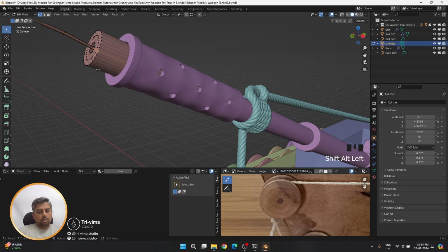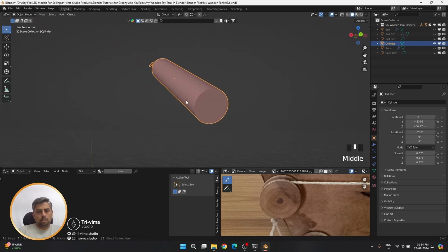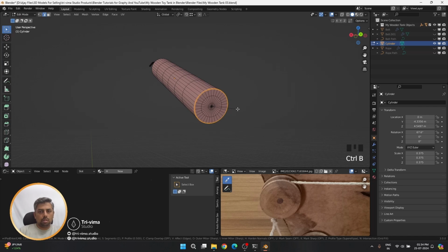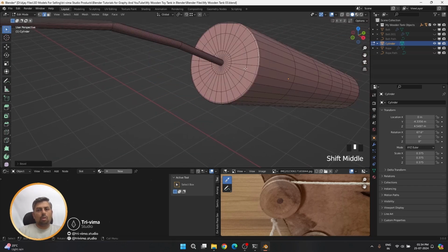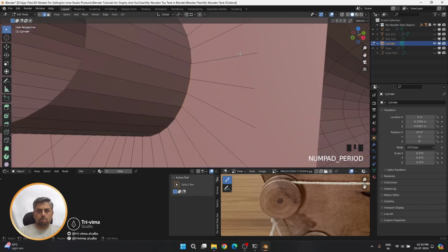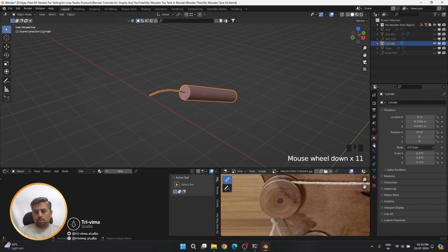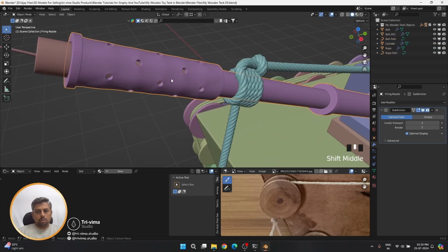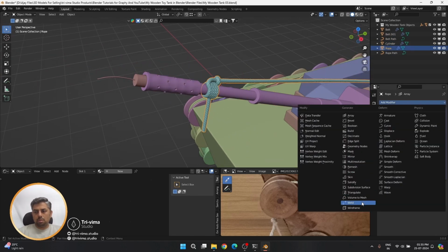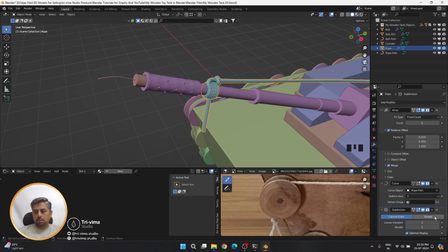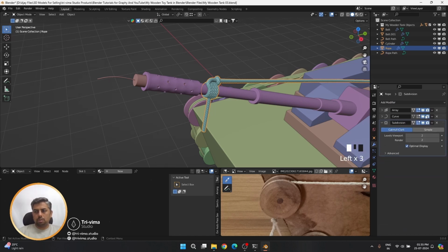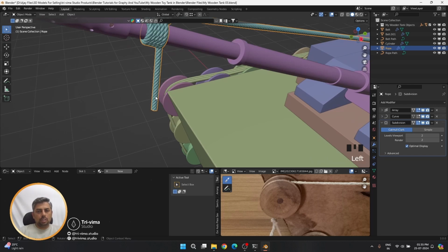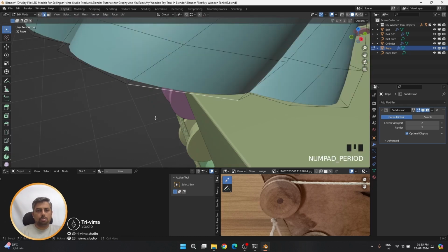And here, it's one bevel. Let's isolate. Take this edge also to the bevel. Okay, this one also let's put a bevel. Although this piece won't be seen, so don't worry. We are not going so close. But I need a little bevel to give it a smooth look. So let's do this here. The same slice, we saw in this part. We'll give this part a subdivision surface and all. And now here I need this to be packed. So apply, and then close up, select.